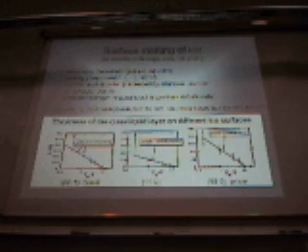And that is something which is very peculiar, because we've heard that lead and other metals also show surface melting, but they show this only on certain facets. And these are usually the facets which are not so densely packed. If you take lead, it's the 110 phase. If you take aluminum, it's the 110 phase. In any cubic material, it's typically the 110 phase, the others don't melt, like the 111. It's a close packed surface where the atoms do not have too much space to move around, and they stay solid as much as we know. Water or ice is the only material we know where every surface melts. In that respect, this is really particular here.